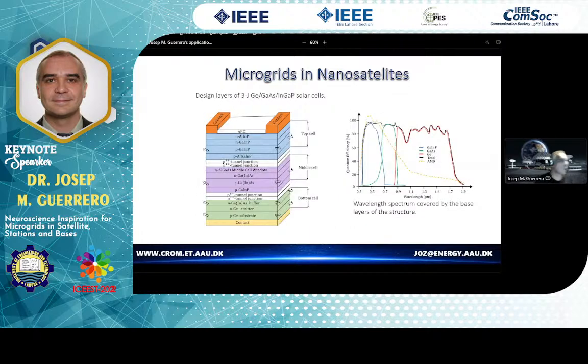So it comes with new technologies, like, for instance, triple junction or even 4 junctions, in which we have, you can see here, very high efficiency for a narrow bandwidth. So if we want to have larger bandwidth for the energy in the solar spectra, then we can stack a number of layers. So today we have 3 layers and even 4 layers for space applications.